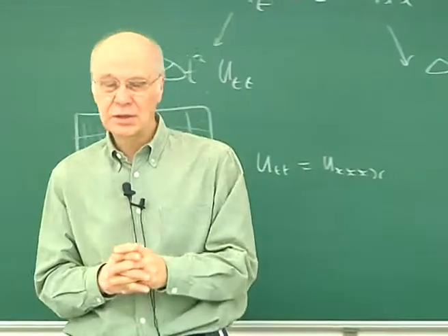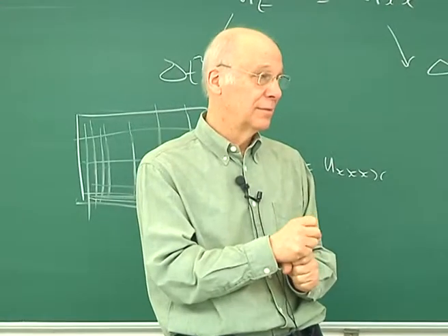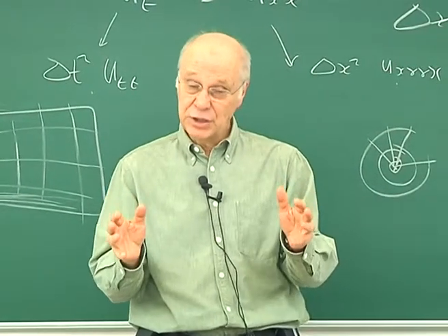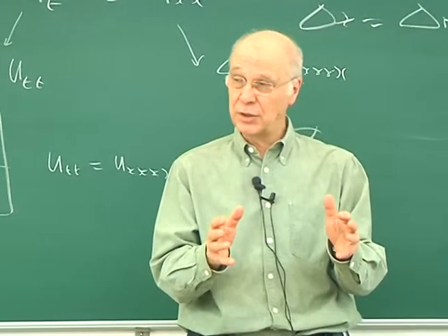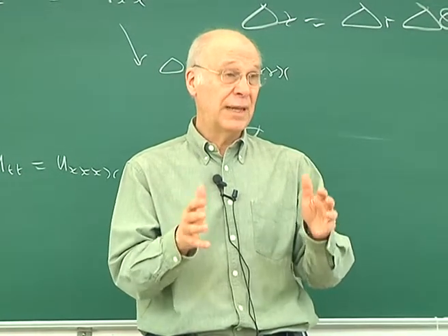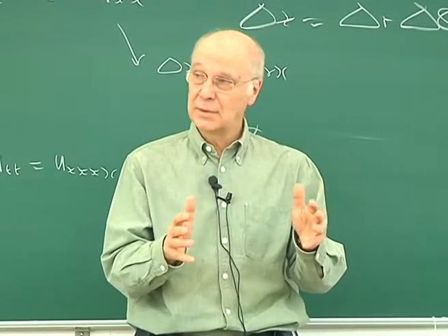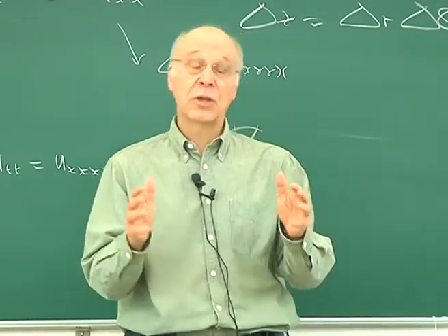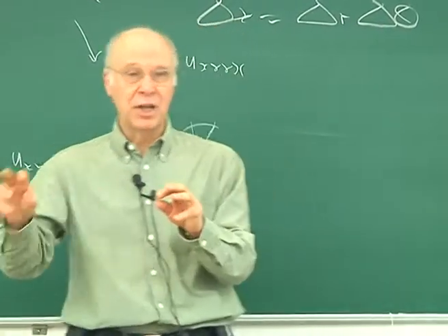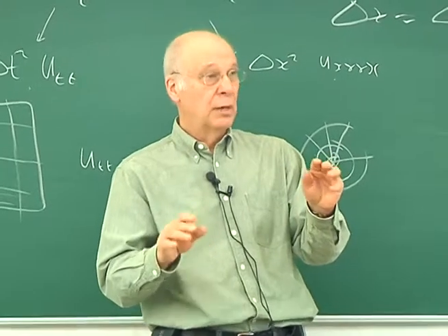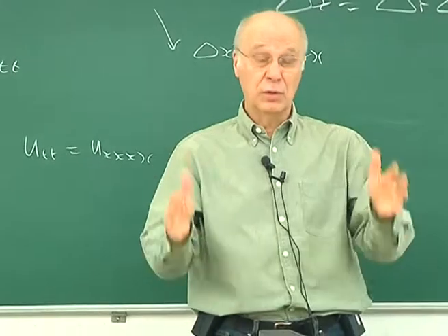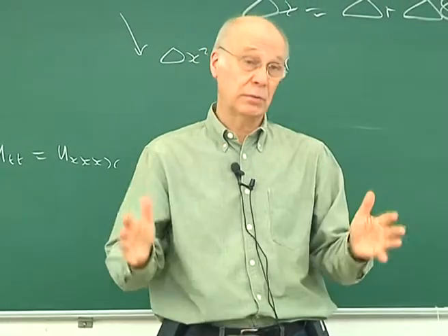You may want to make it exactly 0. And you may want to conserve your numerical scheme, which is an approximation to the momentum equation. You would like your approximate equation to conserve momentum exactly. That's called a conservative scheme. Sorry, global momentum. So it's not conserving momentum at each point because it's only an approximation of the governing equation at each point. But you'd like it to be such that the total momentum is always 0.